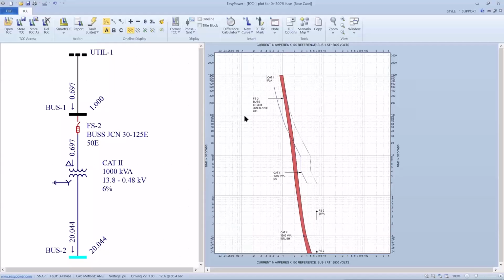Ovide says, why have secondary ground fault instead of primary? Well, it depends on the load. If you have grounded systems on the secondary side, you can have very high fault current with a hard ground on the primary of the Y. I guess if you're saying, why not do secondary ground? The answer is probably it's a good idea to have both, because the transformer is so valuable or so costly. You want to make sure you're protecting it from a through fault.